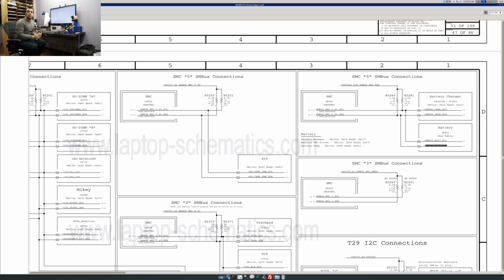Again, if you see that the pulses are only going up to a maximum of 2.6 volts when the data line is being created from a 3.4 volt power line, but it never goes higher than 2.6, is something pulling the line down? I have had that happen before. I had a webcam connector that looked perfect that was pulling a sensor line down to 2.6, and as soon as I removed the webcam connector, I was up to 3.4 and nothing was running slow anymore. So these are all things to think about.